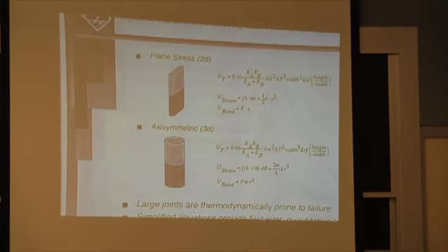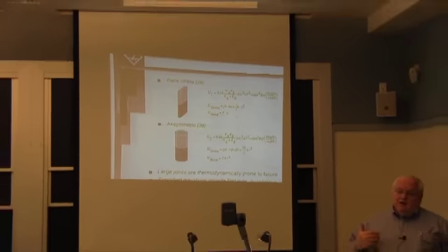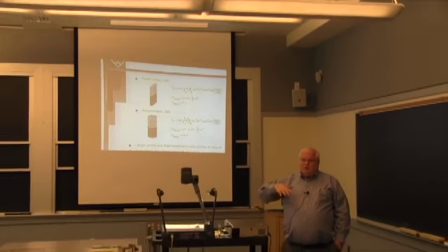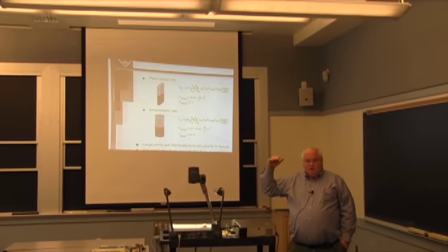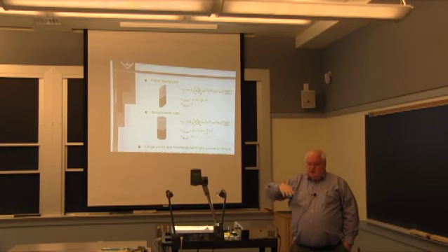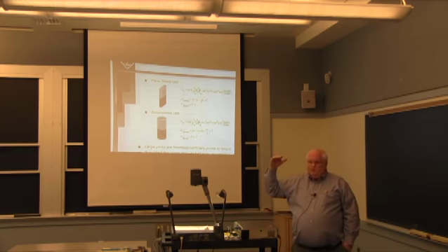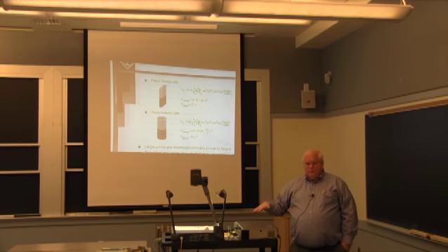And it turns out this thermal expansion mismatch between the materials matters. Sometimes the materials are used at elevated temperatures, and there's a difference between room temperature and elevated temperatures, and then you have thermal cycling, so you get thermal fatigue because you have cyclical stresses from thermal cycling, or you form the joint at an elevated temperature and cool it down. Even if it's formed at room temperature, you have residual stresses because of the thermal expansion.